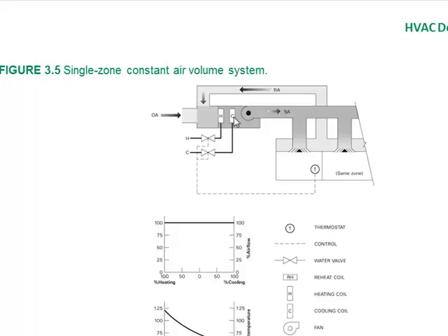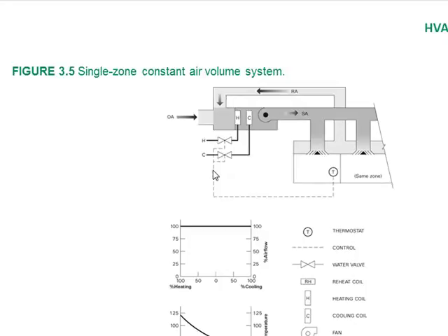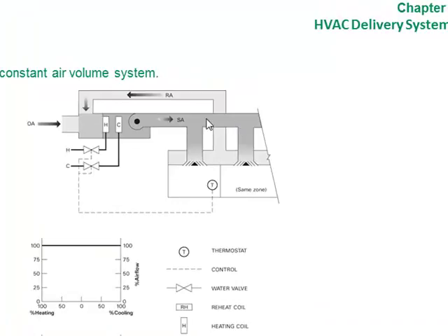So the air is going to blow over that. This thermostat down here sends the signal to which one of these it needs, either hot or cold. And usually on a home thermostat, you can't have both at the same time. It's either on heat or cool. You have to have a pretty complicated system to be able to mix those two, and that's usually only done in commercial. So in your home thermostat, if you have it on cool, when it gets up to 75 and you have it on 72, this may click on. The air would blow over that cooling coil and then out this way to different rooms. These are different rooms you're looking at here. And see, that thermostat's in one room, but it's also blowing into this room.